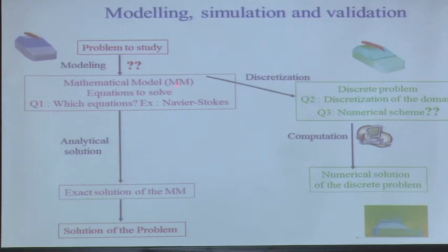This model in physics is based on mathematics, so you have big equations. For us, that would be the Navier-Stokes equations, and you may obtain an analytic solution. Sometimes, if the flow is very simple, for example the flow in a pipe, and the flow is laminar, you may get the analytic solution. Couette flow is another example of flow that you can solve analytically, and it is very important to have some of them, because you will use them as a benchmark.